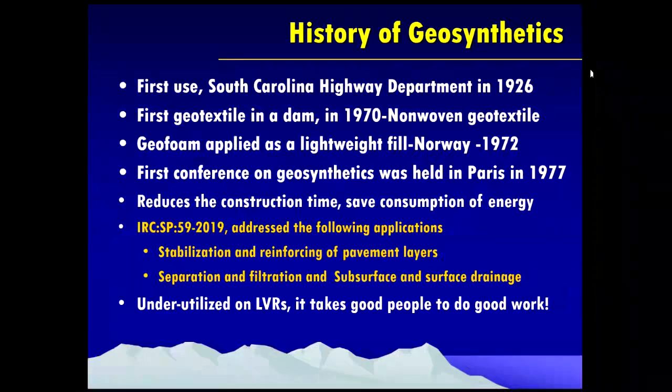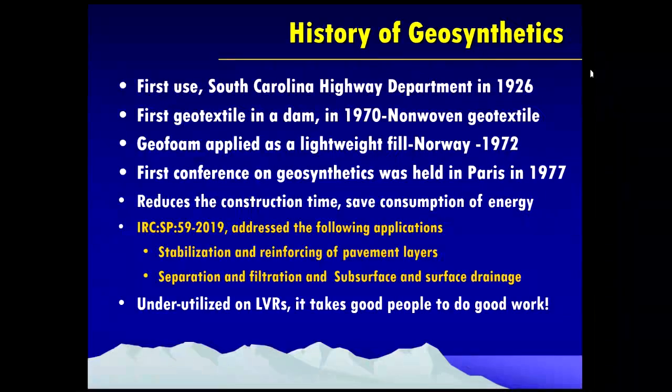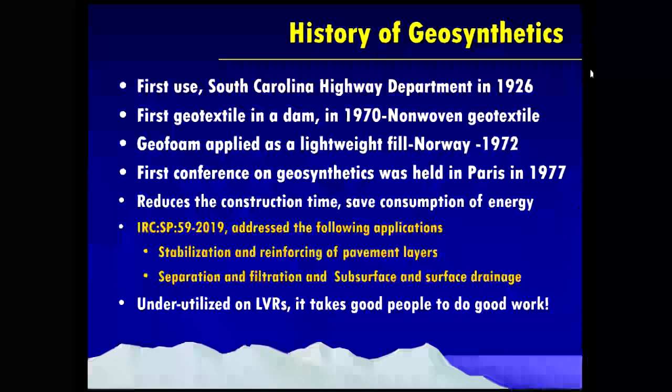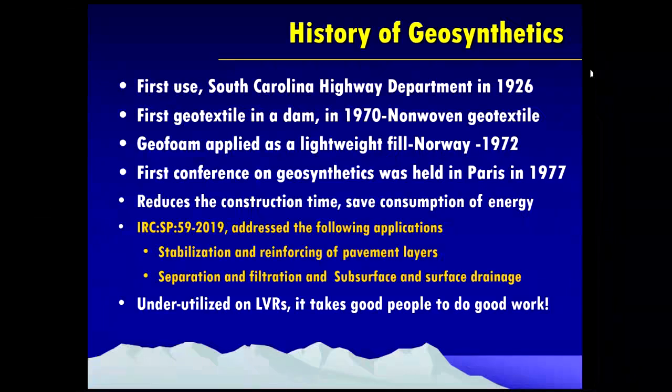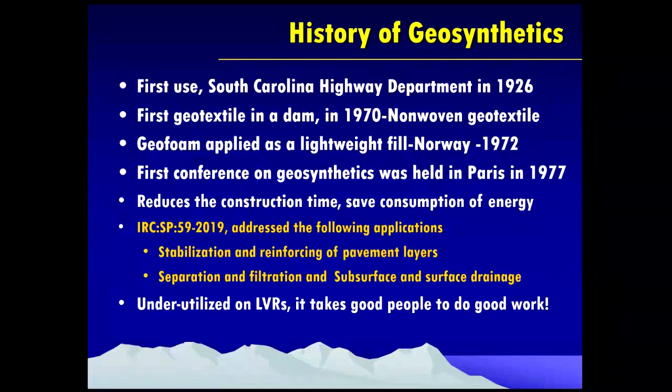These geosynthetic materials help us reduce the construction time, save energy consumption, and also save natural materials. IRC SP 59 2019 has recently brought out a code on using these geosynthetic materials, where they addressed two major applications. One is stabilization and reinforcing of the pavement layers. Another is separation and filtration, and the subsurface and surface drainage aspects of the pavement layers.